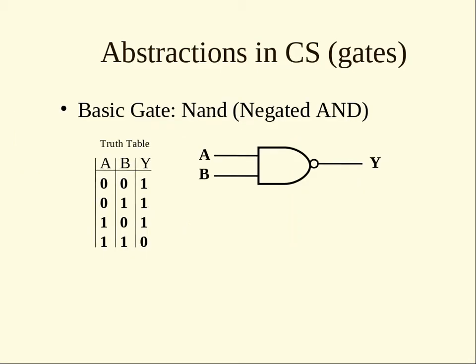All right. So next comes NAND, negated AND. It might be confusing why we're going straight to NAND and not to AND, but that's because NAND is actually a lot easier to draw or to use with transistors. So again, the round bullet is an AND, followed by a circle means it's negating it. So the two inputs are first ANDed together and then negated afterwards, and we call that a NAND, or negated AND.